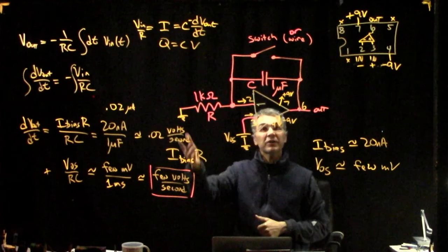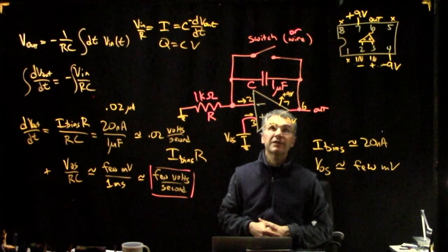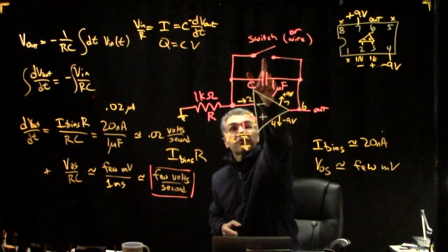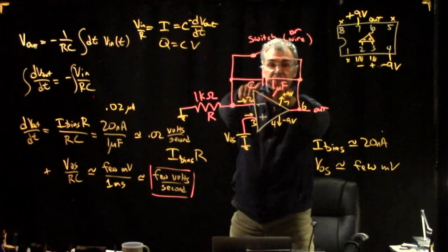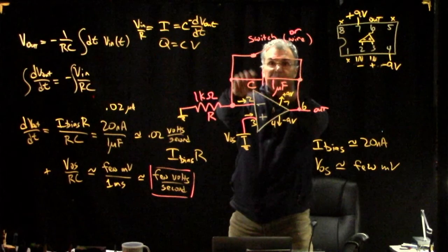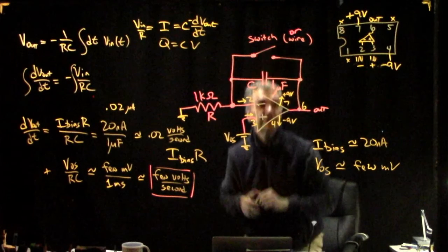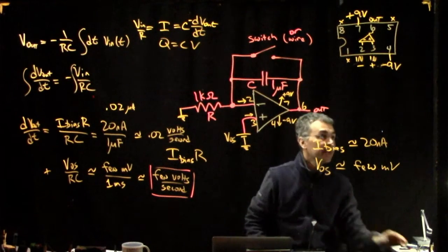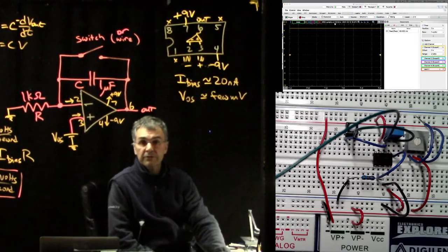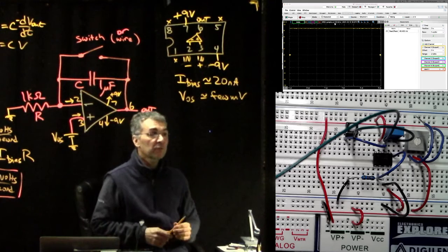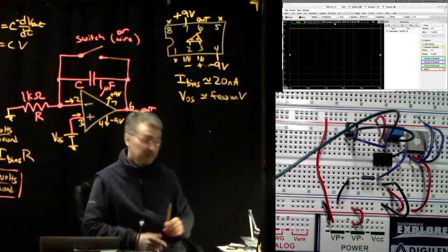And then how do we set the initial conditions so we can start integrating? We've wired up a little push button switch here. So when we close the switch, it removes the charge from this capacitor, and then we'll open the switch and we'll start the integration. So we're going to see that happen right now. Okay, let's go around and see what we have built here.